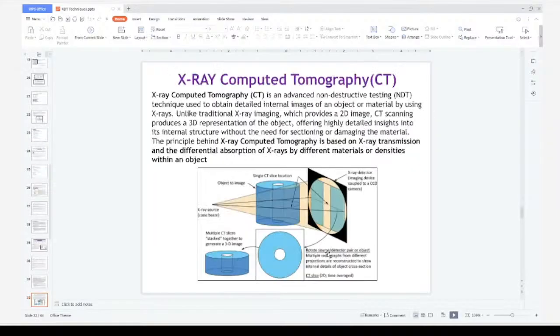What you do here is keep the sensor on the part and subject the part to some kind of deformation, which is an allowable deformation, the stress. What will happen is, if any existing defect is there inside, it will open up and propagate, or any existing problem like corrosion will respond to this acoustic emission and may let us detect it through our sensors.